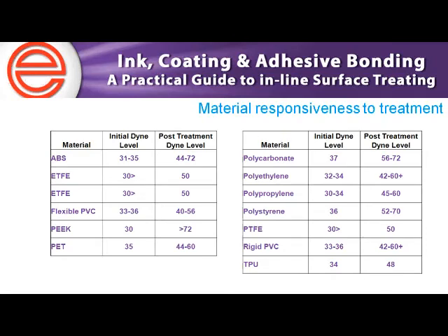Here is just a quick snapshot, and by no means all of the materials that we've worked with, but very common materials that we work with at Enercon. You'll see the material and the initial dyne level. For those of you who are not familiar, a dyne level is a measurement of surface energy. You can use dyne pens or dyne solution.